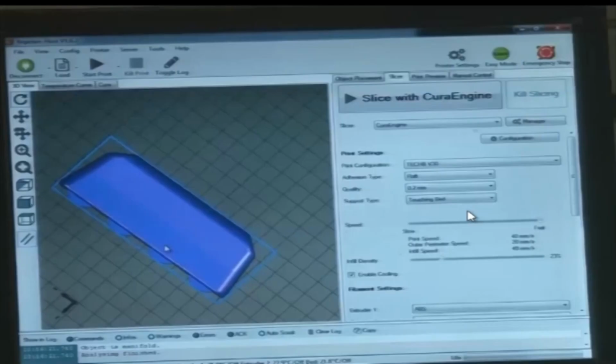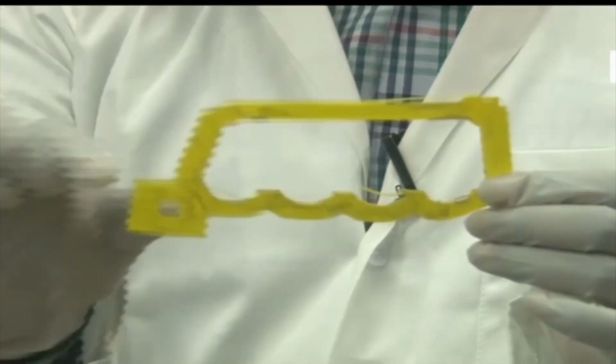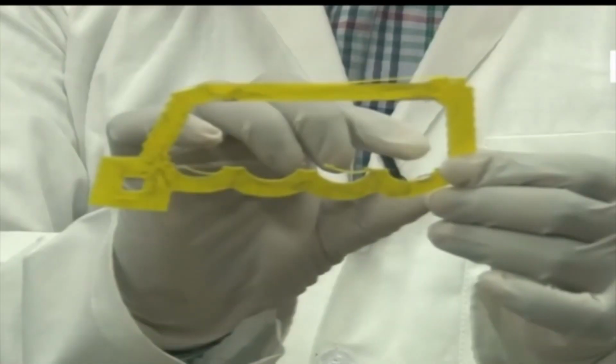So this is brim that is taken off from the job that is prefabricated. This is the model that will be developed. So this is the pocket. This extra material is brim. This whole material is brim. This is taken off from the project that was manufactured before. So this will stick with the bed properly, and this enlarged area, this is the first layer, will provide a good holding with the bed.